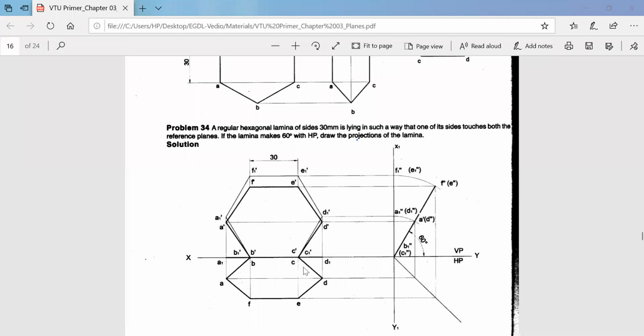So this is done. But since the given side view is inclined, you have to rotate this side view parallel to our XY plane to get the true shape of it. What we usually do in projection of lines, when you have the apparent length and angle, is rotate that parallel to our XY line. Similarly, you have to do it over here.